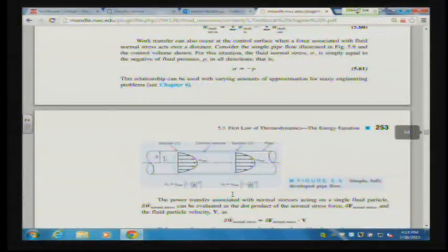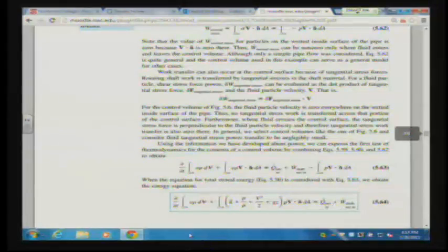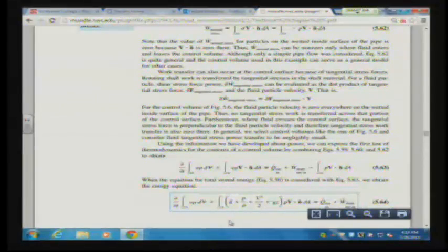And we can just talk about the sections of the pipe. So really, we are coming up with these ideas that all come back to the same place, which is this equation for total stored energy. Now, there's a couple of things I'd like you to see. After we go through this, we have a pressure over rho, V squared over 2, and we have a gz term.